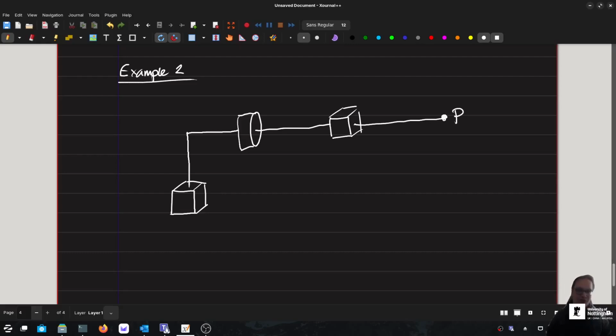First of all, let's draw all of our axes in. Z0 is going to be upwards in this direction. X0 can be in any direction I want, but generally I think it makes the maths a bit easier at the end, so I'm going to assign X0 over here. Therefore, completing the right-hand set, you'll find that Y0 is going to be into the page.